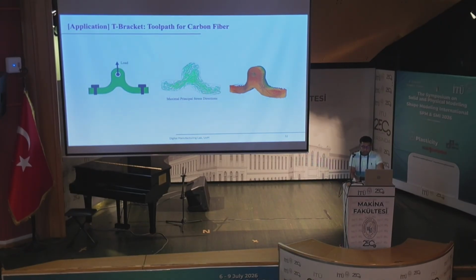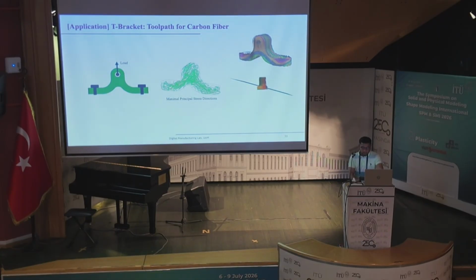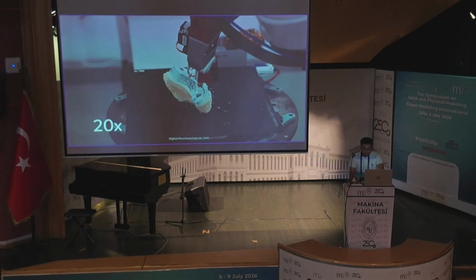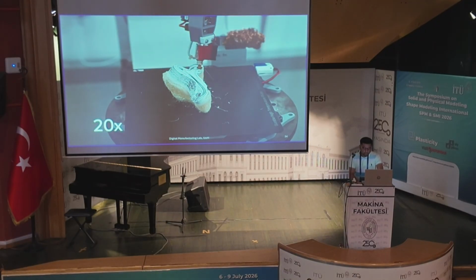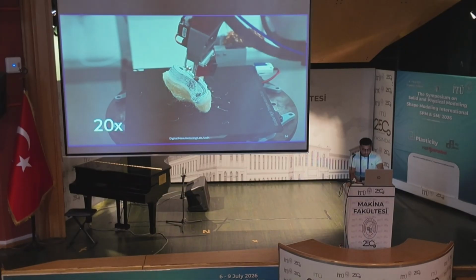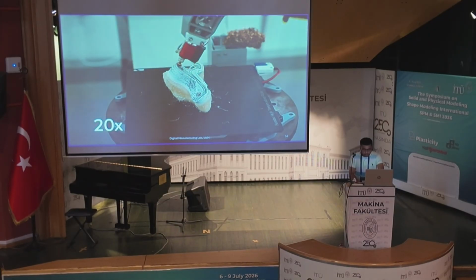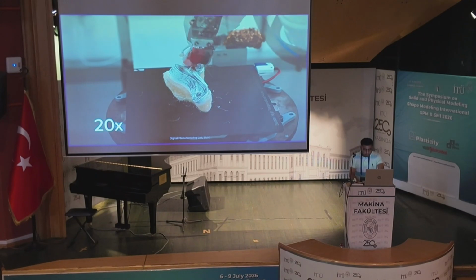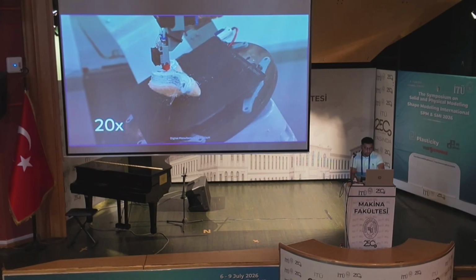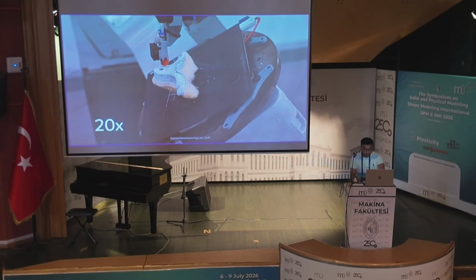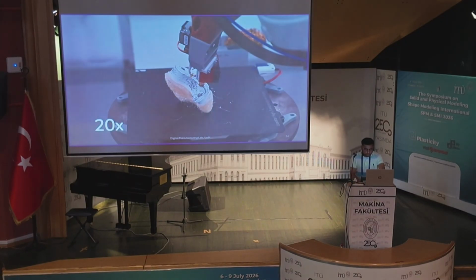One of the benefits of using an implicit method is that we can also add other functions, like here we saw an example of optimizing the setup together with the toolpath and the layers itself. And again, here is an example of how we print the long continuous carbon fibers on the layer. We use the same robotic setup with two different depositions. So here we print the base material, and then the other nozzle prints the continuous carbon fiber.